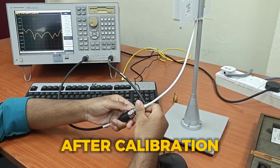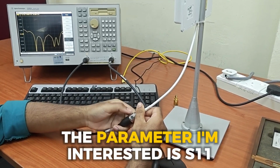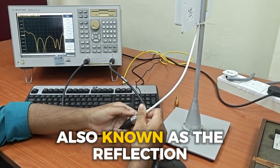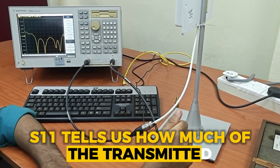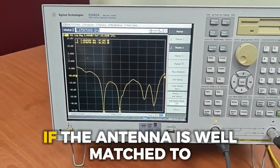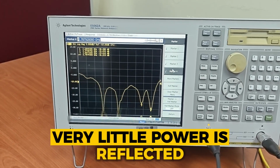After calibration, the antenna is connected to port number 1 of the VNA. The parameter I'm interested in is S11, also known as the reflection coefficient. S11 tells us how much of the transmitted RF power is reflected back toward the source. If the antenna is well matched to the transmission line, very little power is reflected and most of the power